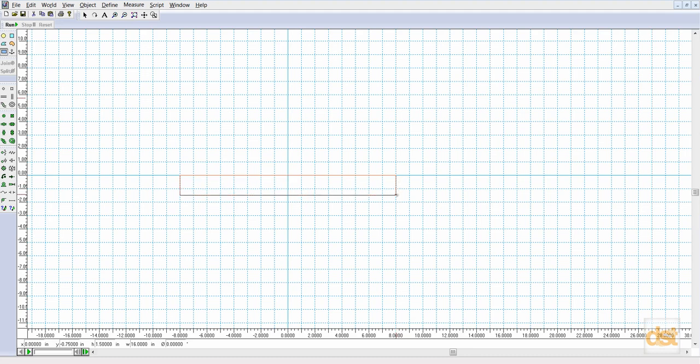And y is arbitrary at this point. It really doesn't matter. This is just simply going to be anchored to the background. So I'll just find some arbitrary thickness right there and click. Notice that with our object selected, it's showing us down here the height, the width, and the current orientation. So we've created a base that was 0.75 inches in thickness or height and 16 inches in width.